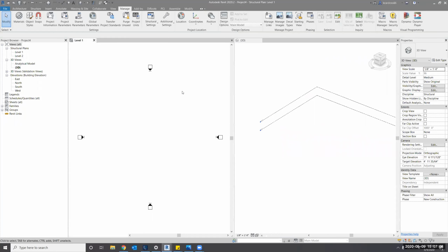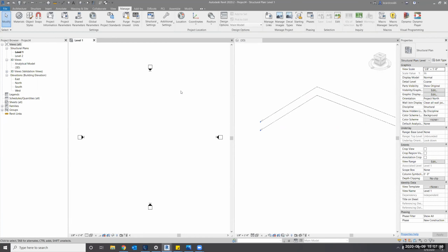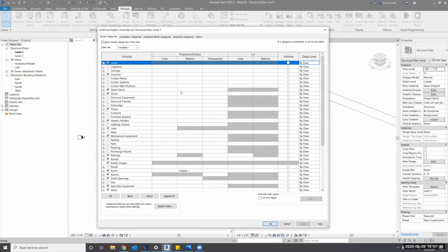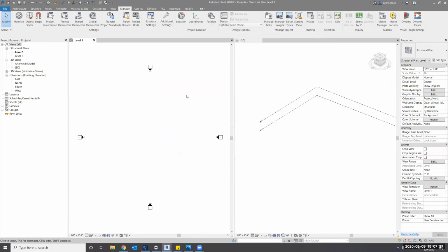And now over here in plan view, since we're primarily going to be working on foundations today, let's go ahead and start adding our grids, okay? Before you add your grids, it's a good practice to know where you want to place the grid. I like using the internal points that Revit has. So if we go to our visibility graphics, shortcut for that is VG, okay? Or for those of you that are still learning, if you come over into the view properties of your plan view, it's also right here.